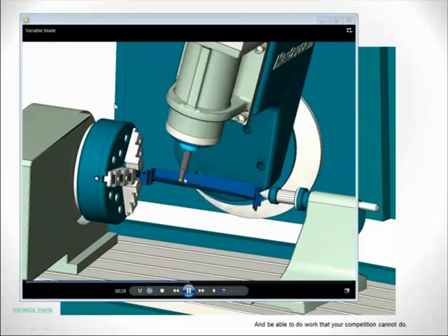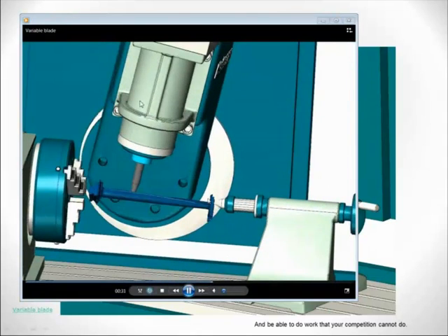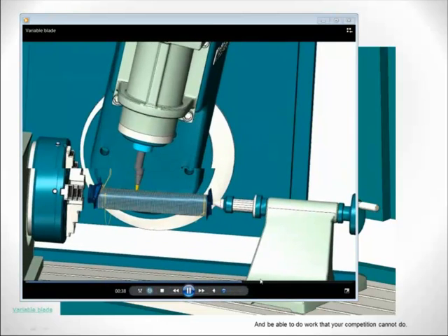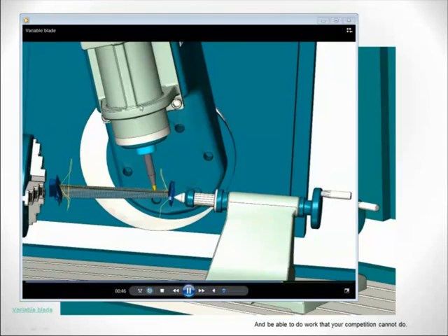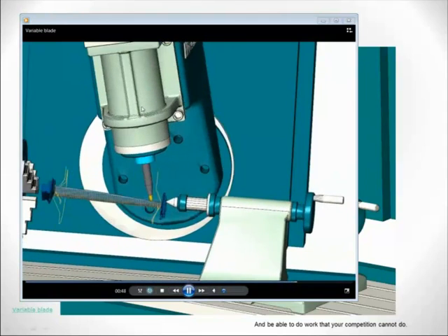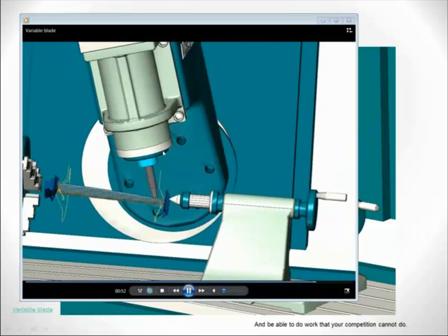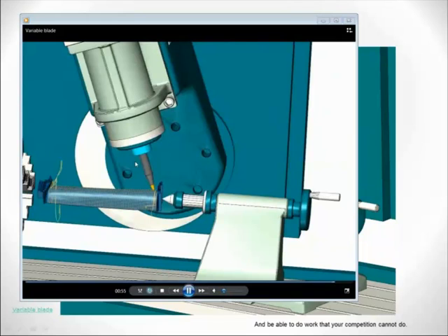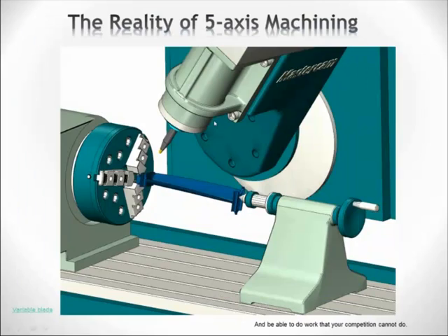We want to change that angle so that we can get to this face. So let me move it up. That is our toolpath, and I'm just going to move it along so you can see how that angle changed. And it's changing gradually as you go into the other side. So this is what some people call true 5-axis, because it's continuous 5-axis machining, not indexing.